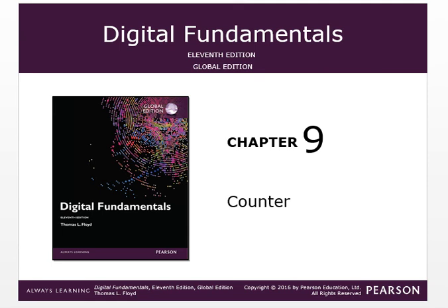Asynchronous counter is otherwise called a ripple counter. In an asynchronous counter, the clock is going serially. The clock is given to the first flip-flop, and the output of the first flip-flop acts as the clock for the second flip-flop, and the output of the second flip-flop will act as the clock for the third flip-flop, and so on. But in a synchronous counter, the clock is given simultaneously to all the flip-flops. So a synchronous counter is very fast compared to an asynchronous counter.